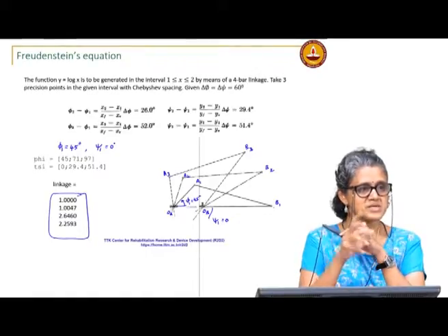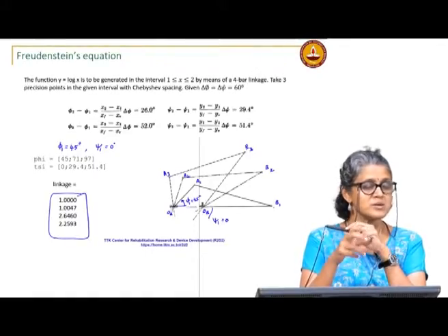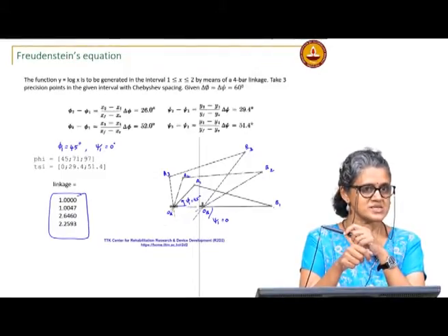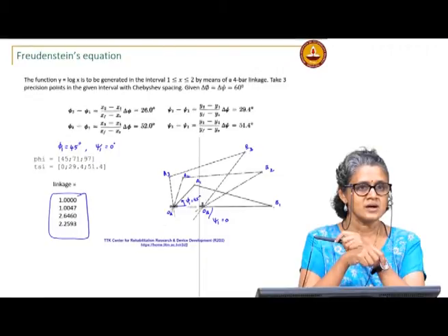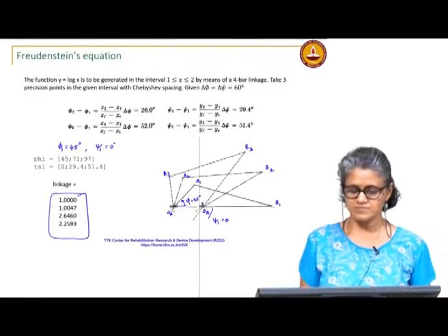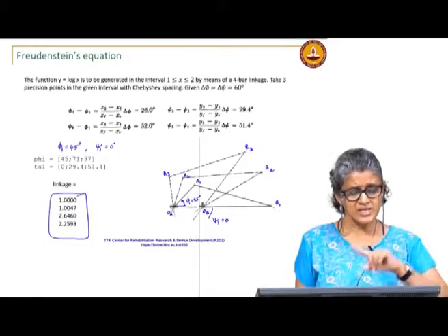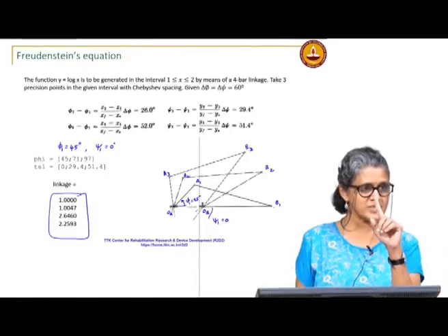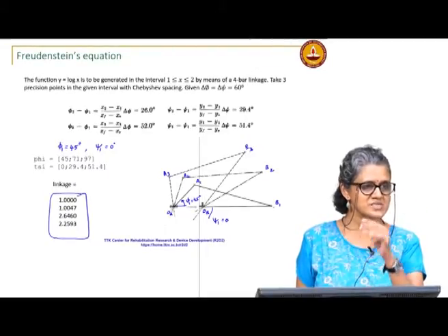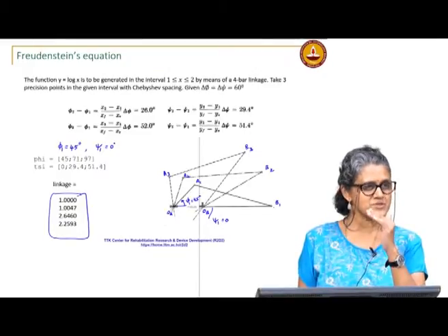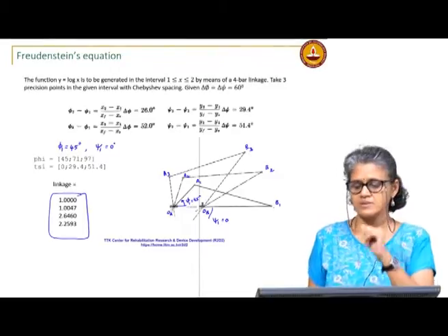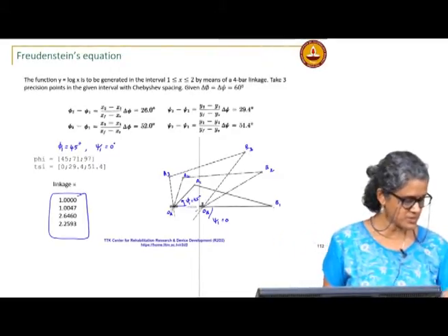So, that is a solution I get, but here I am able to specify. The geometric methods may have limitations because of the parameters I have to specify for the construction, I may be limited in some way. In this case, I am able to specify both the precision points. There in most cases I only worked with the 2 angular displacements, and I specified only one of the initial angles. So, that is something to keep in mind.